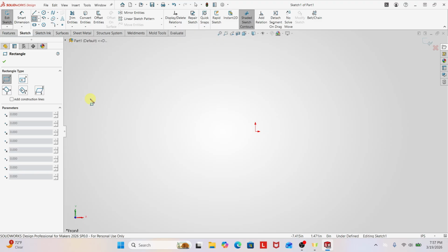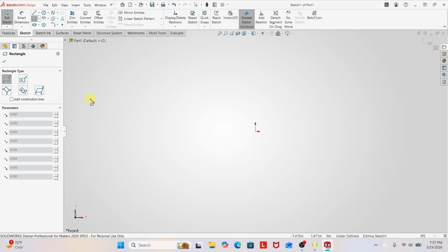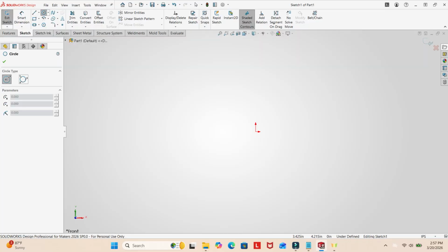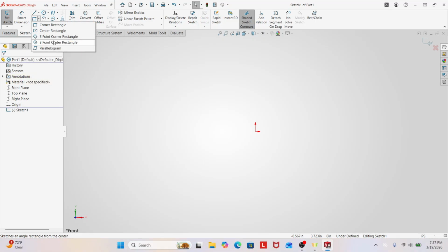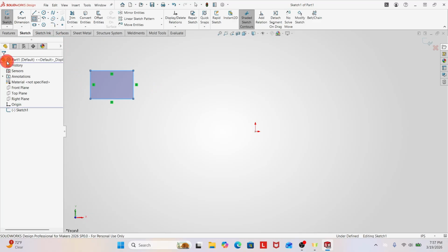This set of options is called the property manager, and it contains different tool settings you can change depending on the tool you are using. So you can expect the shown settings, or properties as they are officially known, to be different for each individual sketch tool. For instance, here we have the ones that would show up for the circle tool, and here we have the ones for the line tool. The property manager will replace the feature design tree when a tool is in use, and will go away once we are done using that tool.